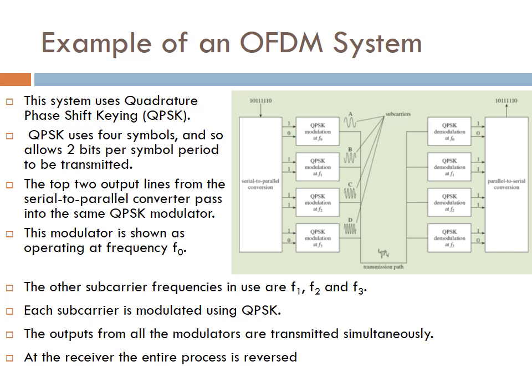It's not immediately obvious what constitutes a symbol in OFDM. Let's take the system of the following figure. Each subcarrier carries a 2-bit number and so has 4 signaling states. By taking the system as a whole, how many symbols are there? To answer this question, it is important to remember that with OFDM, the receiver receives all the subcarriers together.